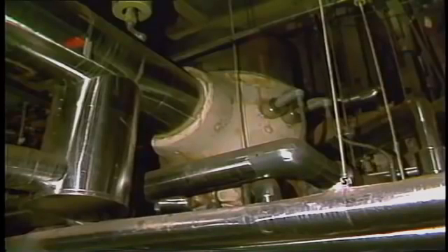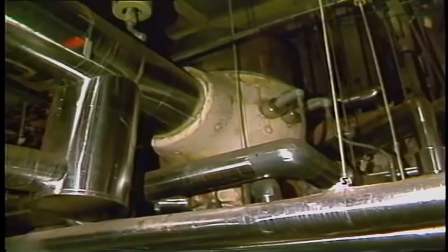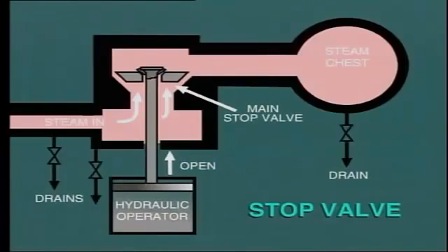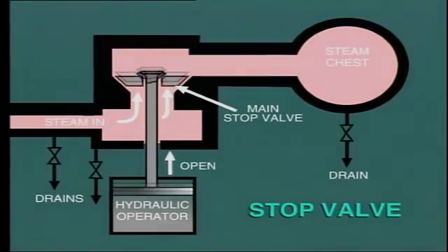An extremely important test maneuver is the exercising of the turbine stop valves. The test circuit allows the stop valve to partially close and then open again. This test is performed daily in many plants, and the objective is to make sure that the stop valve does actually move and not remain frozen in the open position, as has actually occurred on some occasions.